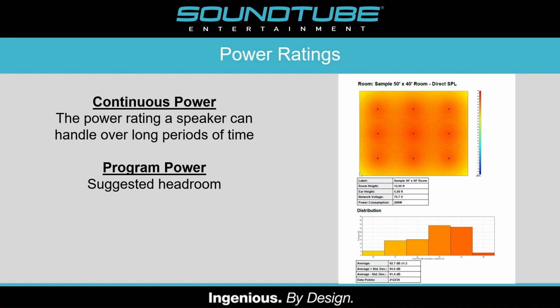These ratings are vital when calculating amplifier power to a speaker, as underpowering can send the speaker a square wave and damage components. Overpowering can melt voice coils.